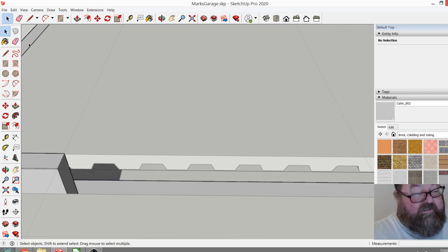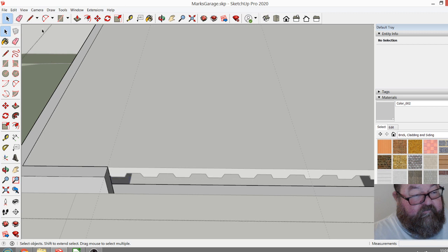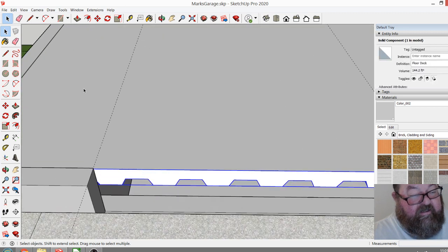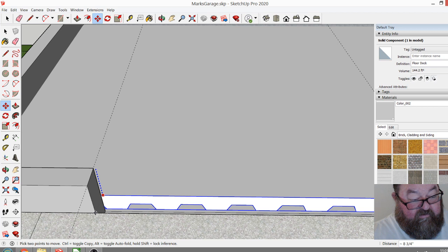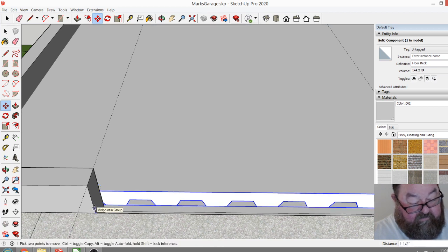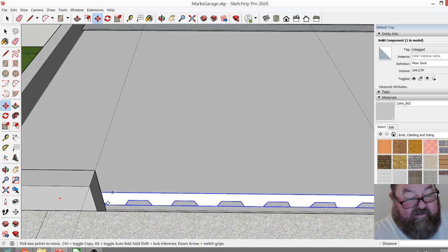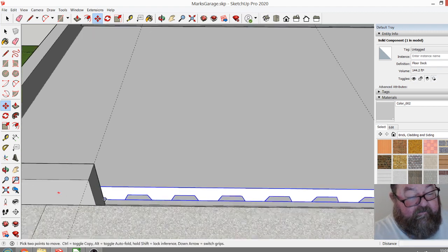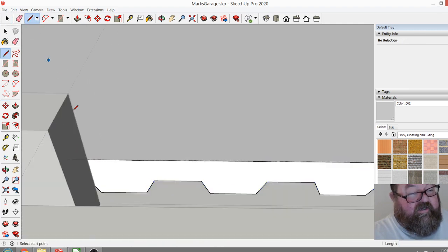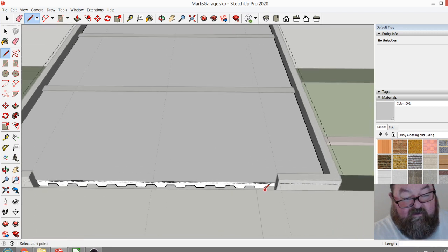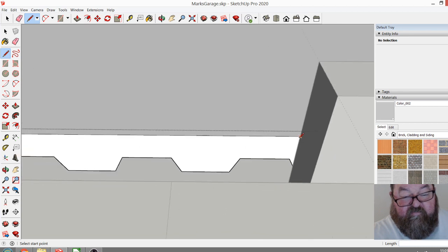This would go down to flush with your driveway. Now you might raise it, you might keep it raised up an inch or whatever. Probably not a bad idea. Then you could put some sealant there to keep water from running down between your driveway and the wall. But this system, the concrete would be poured.